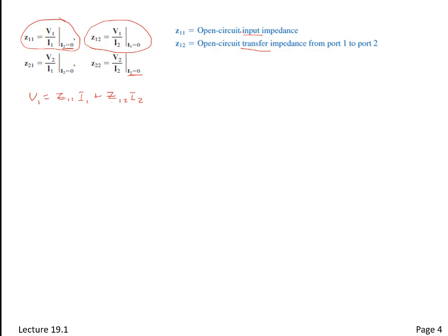These you've typically measured, these are like the Thevenin equivalent resistances or impedances, right? So these are also referred to as the driving point impedances, and the others, the 1,2 and the 2,1, are the transfer impedances. So it's the same thing in reverse to the opposite side. Okay? So just some terminology there, but this idea that you determine these Z parameters by open circuiting the other terminal, right?